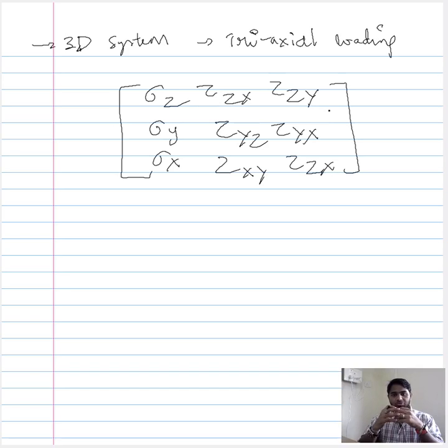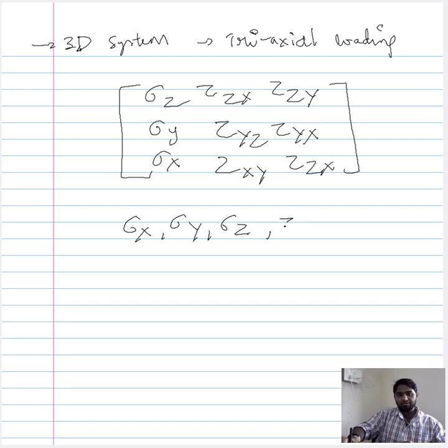So you can reduce those, and when you talk just about independent stress components, you just need 6 independent stress components to describe the condition experienced by a section in the 3-dimensional material experiencing triaxial loading. If you write down these 6 components, you will have 3 normal stress components and 3 shear stress components.